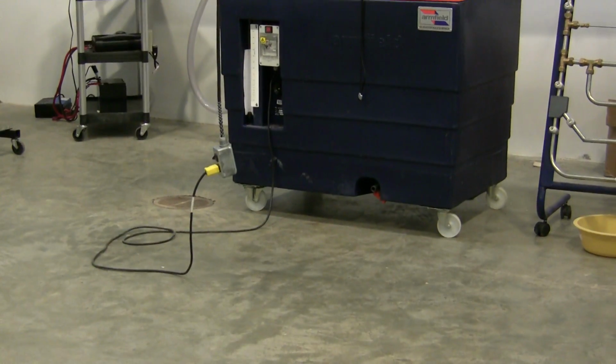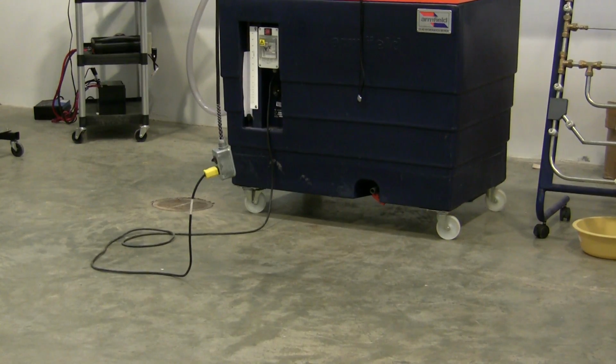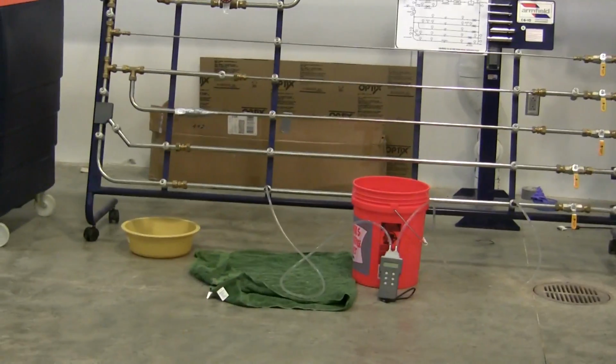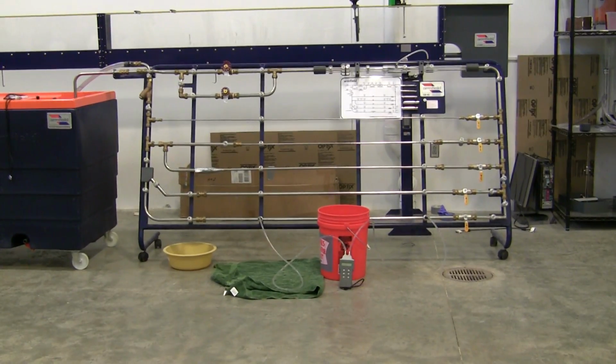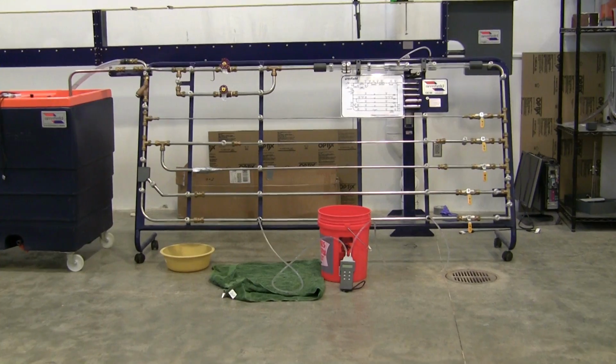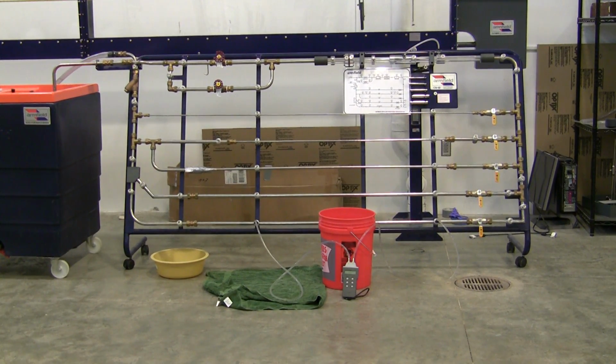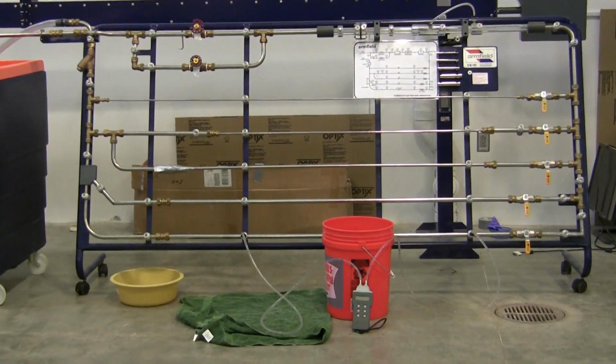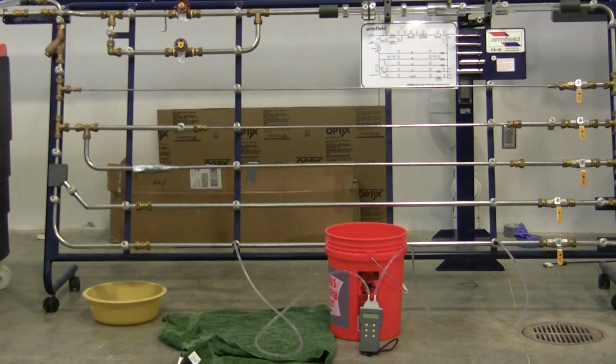Another safety issue is that the cord is a possible trip hazard. I'll try and tuck that underneath the bench to the extent that it's possible, but still we have to be aware of our surroundings to make sure that there are no trips or slips. Because there will most likely be some additional water spraying out of the bench or dripping from the pipe rack, we have to be vigilant to make sure that none of this slippery concrete gets wet, because that could cause a slip hazard. One other final thing is that this pipe rack is itself a little bit top heavy, so make sure not to push on it or pull on it. As I'm putting in the pressure measurement tubes, I'll try and support that with my hands.